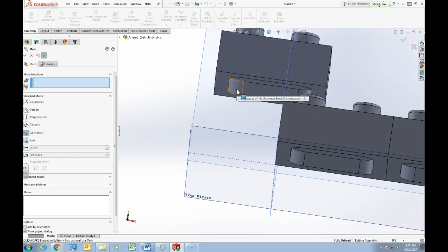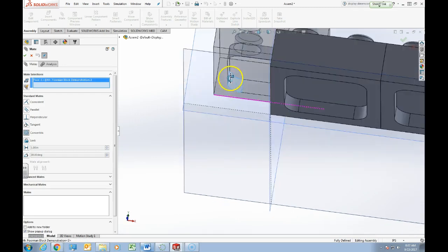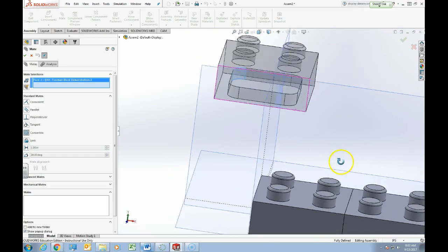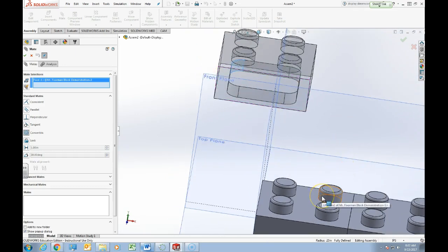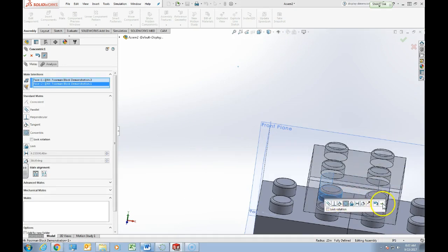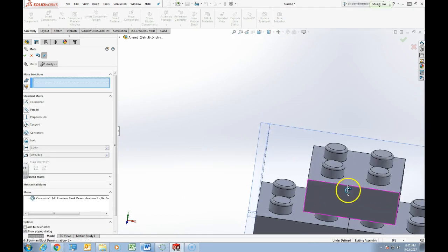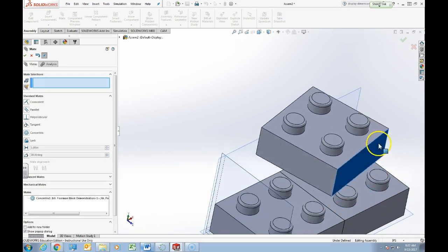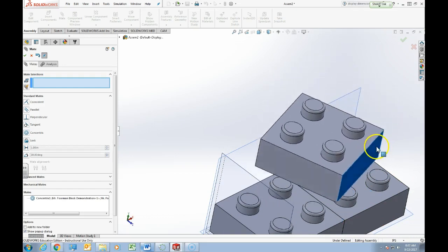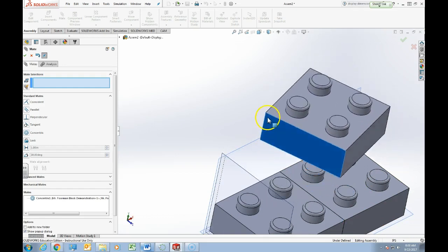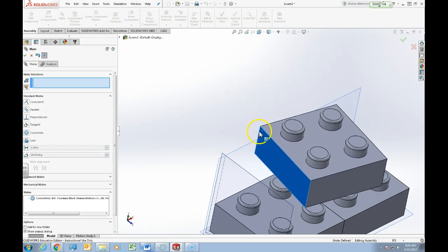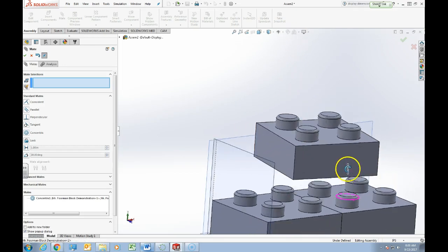So I'm actually going to click on, say, that rounded filleted edge of the bottom part. And then I want it to be aligned to that part right there. And there is a button that says lock rotation, but I'm going to hold off on that for a second. So now if I click and move this part, you can see that it can move up and down, and it's actually free to rotate theoretically. So it's as if it's riding along that boss extended all the way up and there was a hole and you could spin it around that. So notice, cool, that's aligned there.